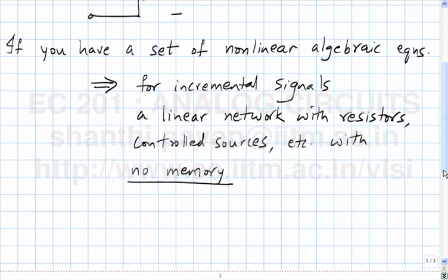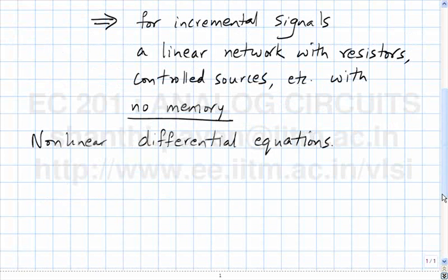Now, if you have a network described by nonlinear differential equations, what can you expect to get for incremental signals? In the first case, when we had nonlinear algebraic equations, for incremental signals you would get linear algebraic equations.